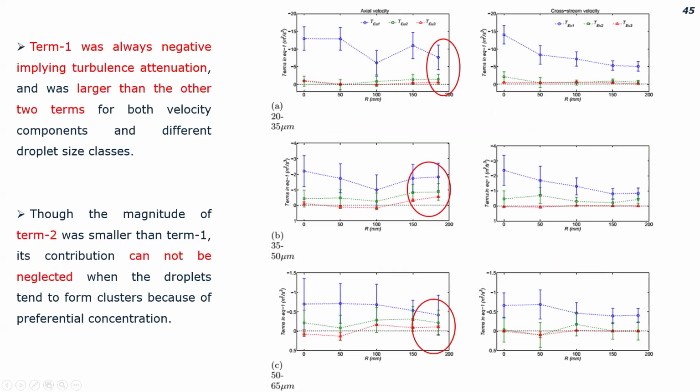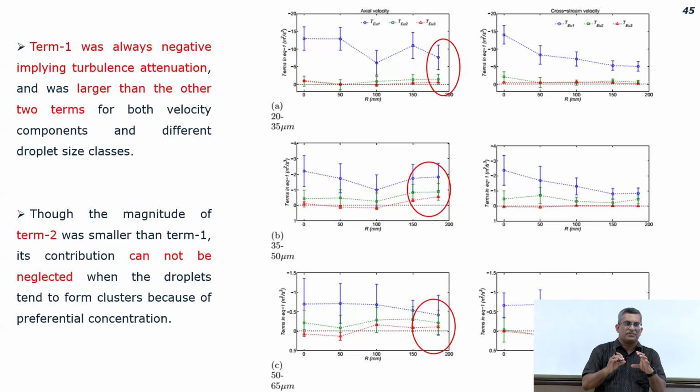And when is that important? When you have particle clustering. So if particle clustering in a flow is occurring, then you can expect correlation between local concentration of particles and the particle velocity itself. Okay. This is because when particles tend to cluster, locally their velocity changes. Okay. It is difficult to say whether it increases or decreases always. It is not universal, but definitely it changes. And that influences turbulence modulation. And that was shown here basically.